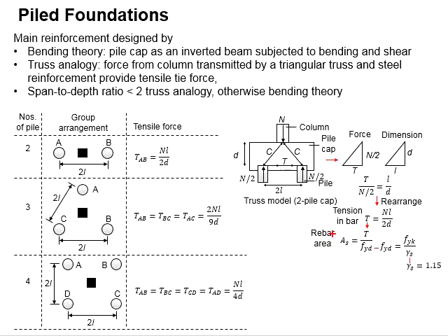This is done by having the reinforcement bar area multiplied by the design yield strength of the reinforcement bar needs to be equal to the tensile force, as written in this format. The design steel strength is given by this formula of fyk divided by partial factor of safety of the steel, which is equal to 1.15.